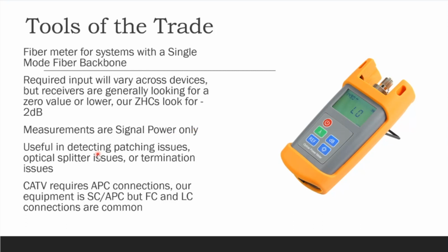And what do we find? Well, when you're designing a system, your fiber reading should be relatively similar, right? Like if I launch from my head end at 10.5 dB, I go through a 1/8 splitter, I'm at 0 because I just lost 10.5 dB. I should be close to 0 everywhere throughout the system. So if I'm going closet to closet to closet and I'm testing and I get 0, -0.5, -0.5, -5, well, then we have to do further investigation onto this port that's -5, right?